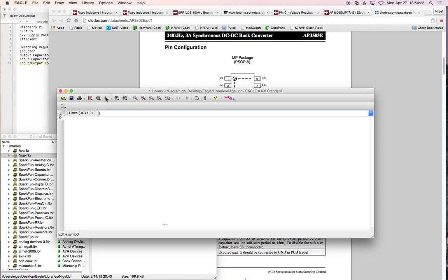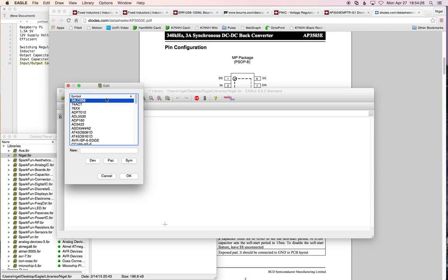So first off, we will go and create a new symbol. In this case, we're doing a specific part, and so we're probably going to do a specific symbol new to it. In other cases, like I was talking about with resistors, all resistors are going to have pretty much the same symbol. All photodiodes pretty much have the same symbol. And so you can have different packages that use the same symbol to reference different physical parts, but they all are the same in terms of a schematic.